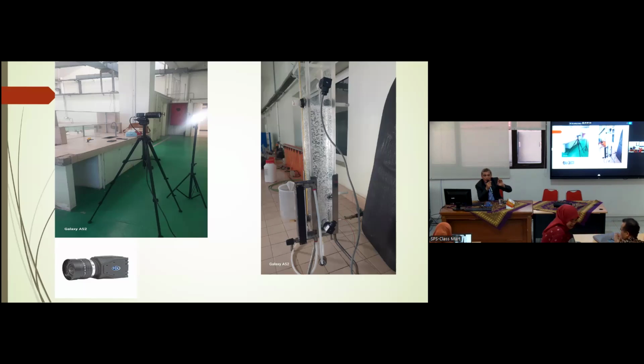It's a question of bubble diameter, number of bubbles, and velocity of bubbles, because the velocity is important. I need a slow velocity to have time to recover. If the velocity is such that the bubbles quit the solution immediately without flotation, I have to master this aspect by different techniques.